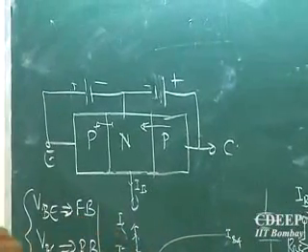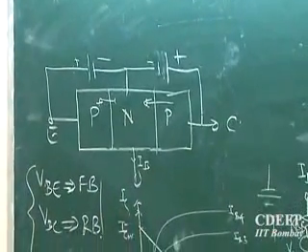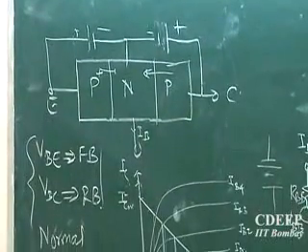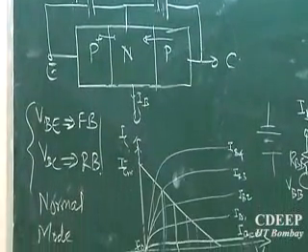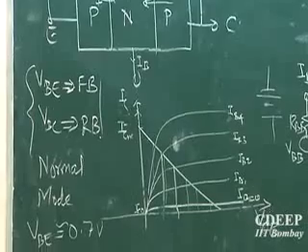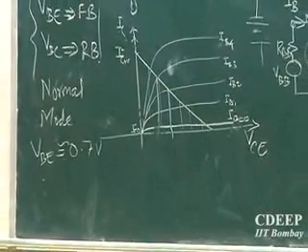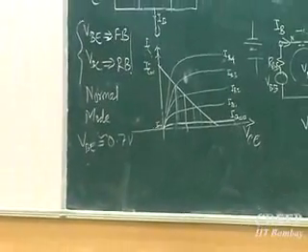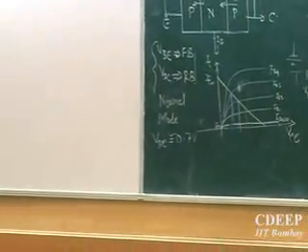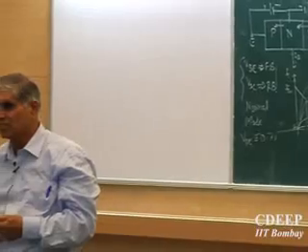Huge carriers will come from the collector side and also from the emitter side, and therefore the base current starts increasing, because excess electrons must come in to neutralize. That means an increase of base current beyond this value essentially means the base-collector junction internally gets forward biased.